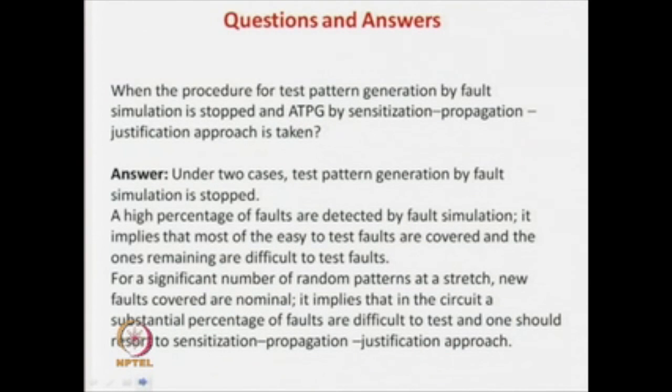For all other cases like serial, deductive and concurrent, we do not at all think about the memory or the parallelism of the computer. We rather think about the fault list size and the affected gate list size, and accordingly we attach them to each gate. That depends nothing on the parallelism of the computer, it is just a program. We compute that for this fault gate list, these are the fault versions you have to add; for these gates, this is the fault list you have to add, and we just keep it. We do not think about the architecture or the parallelism available. A gate has so many faults in its fault list, just keep them.